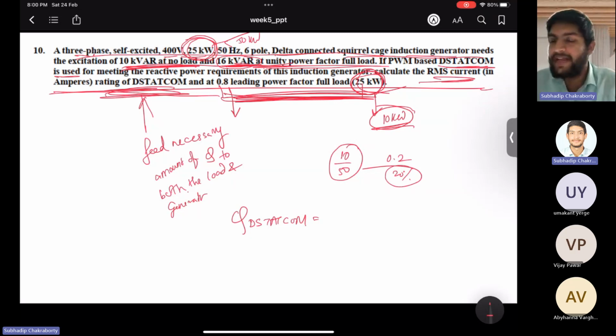If the source is supplying active power, then it is positive. If the source is supplying reactive power, then also it is positive. If the load is absorbing active power, then it is positive. If the load is absorbing reactive power, which is so for lagging loads, then it is positive. It is written like that as per a mathematical convention, and we do it for a reason, to infer from that whether the load is reactive or active.